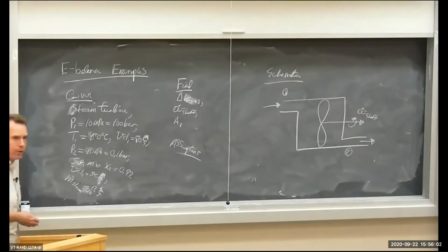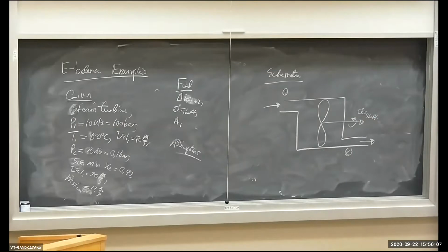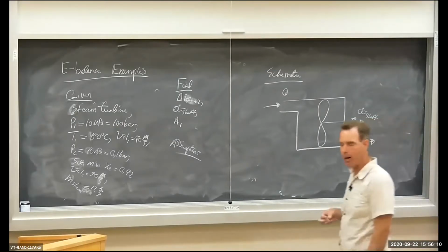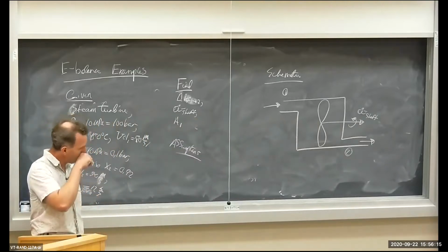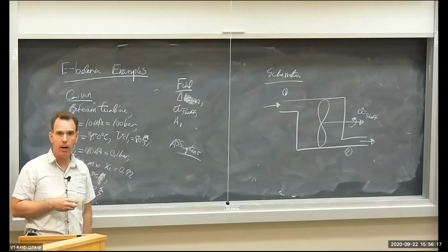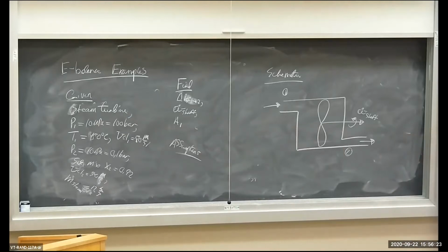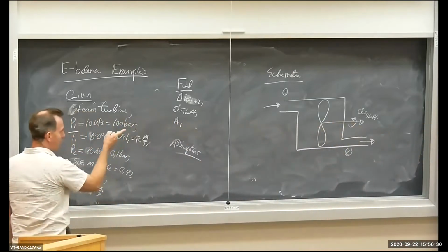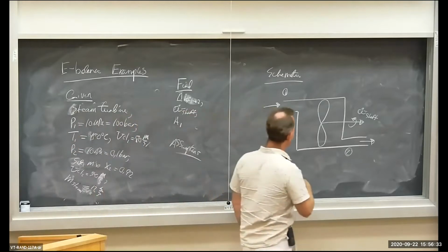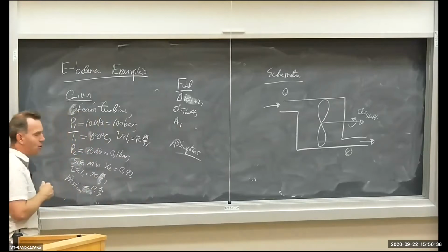All right, let's go through and do another example here. Instead of having an air nozzle, we now have a steam turbine. Remember, a turbine produces power, or shaft power in particular. So it works off of steam, not air. So obviously we're going to be using steam tables and saturation tables to do this particular problem. So we have a steam turbine that takes high pressure steam. The inlet is location 1, the outlet is location 2.